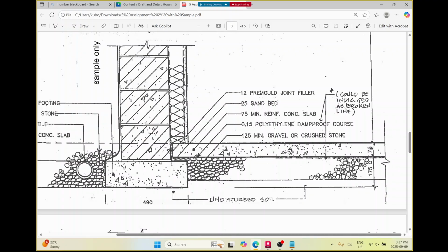Now we have a concrete block wall and a concrete floor, but in your basement you sometimes don't want a concrete block wall, you like to have drywall and some nice finish. Plus you want some insulation, you want it to be super cold. So what they did here is this little rectangle with an X, that's a 2x4 that you're slicing through. If I wanted to cut through this wall and draw what I see, it may look much like that, but if I had a 2x4, you know what a 2x4 looks like, right? Just a piece of wood lying flat on the ground, and I cut through that, you would represent it like this.